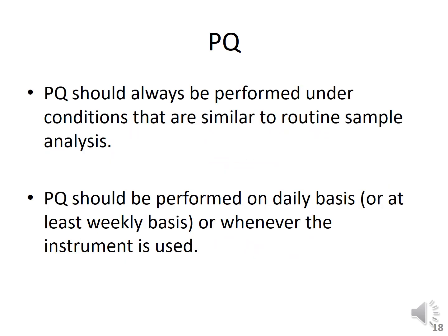Now, the performance qualification PQ should always be performed under conditions that are similar to the routine sample analysis. That means it is important that you do your performance qualification under all those conditions which are similar to the routine sample analysis. If you are doing the performance qualification under somewhat different conditions, that will not be worth working on,